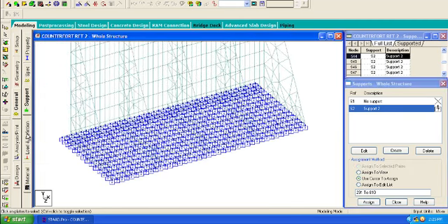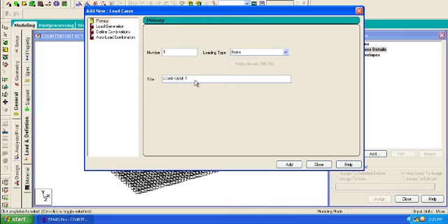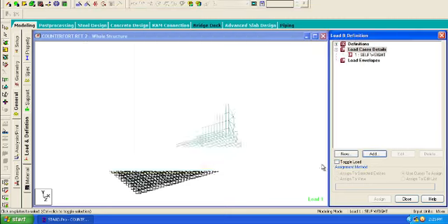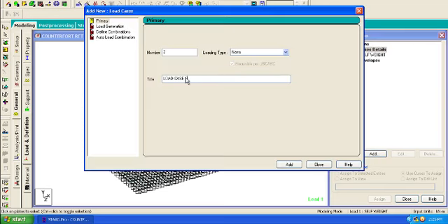So we have to define our loads, load case details. We treat this as the self weight of the soil. In another load case, since we'll be using the same factor of safety, let's allow surcharge and let's say earth pressure.